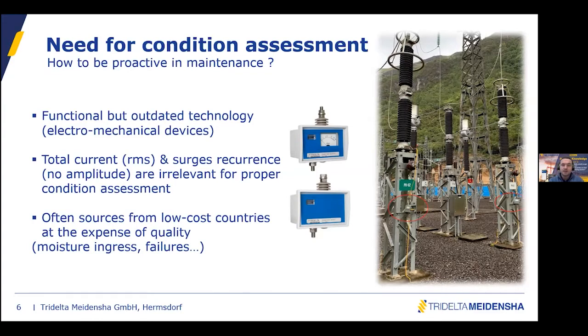The other one is the counter itself, that will give you the number of over voltages that could occur on the surge arrestor on your specific phase. This is also just a number. It does not provide you the time, the date, and the amplitude of the surge, of the impulse. So it's pretty limited.